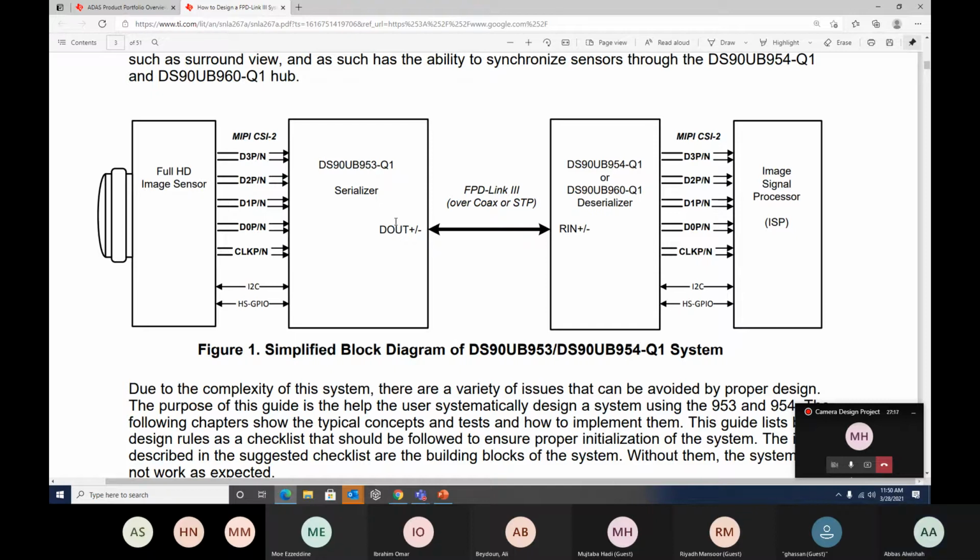You could have one reverse line of the data out to the data in, and then you have that potential issue where you have to start debugging: is the issue here or is the issue there? Or it could be the way the structure is done hardware-wise in terms of laying out the PCB. And the software engineer thinks, okay, I have an issue with my code, and they could go out there and rewrite their whole code for 3 days when it's a data continuity issue.